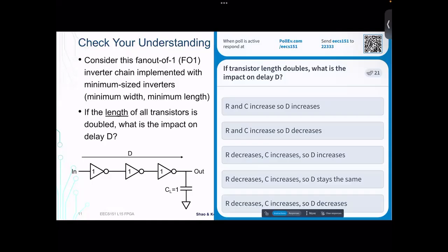So this is our transistor. This is the source, this is the drain, this is the gate. So the channel would be under here, right? Remember, when we talk about resistance, we're talking about the resistance of this channel when it's turned on by the gate. It's the gate size that determines how much channel there is for current to flow.